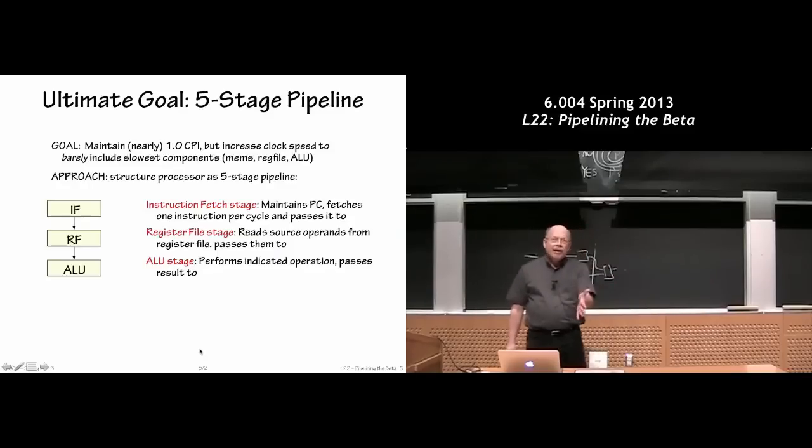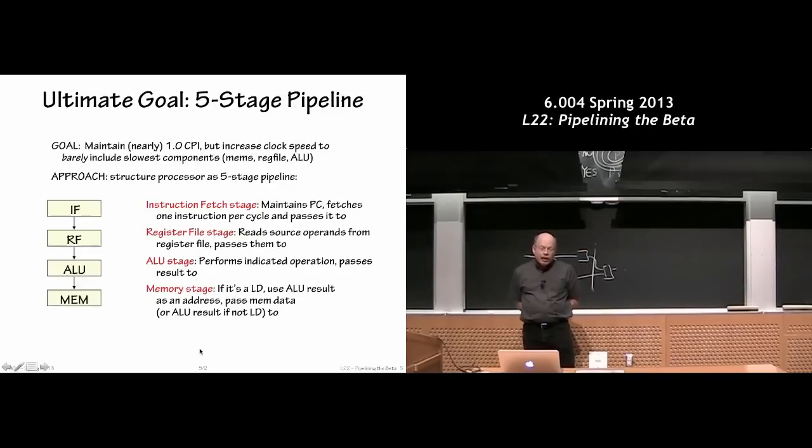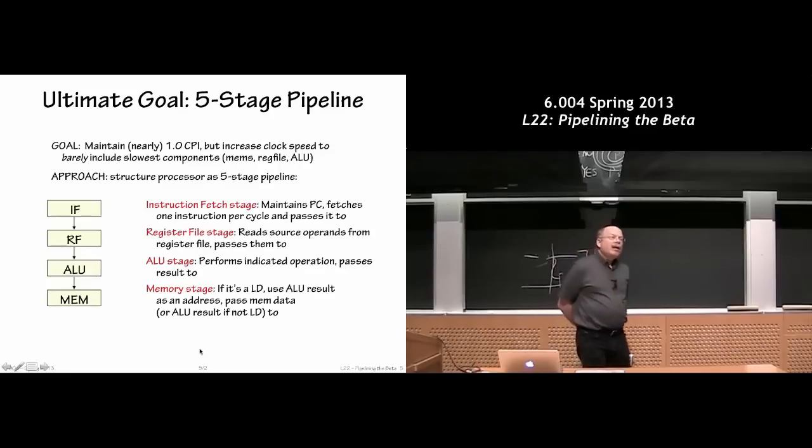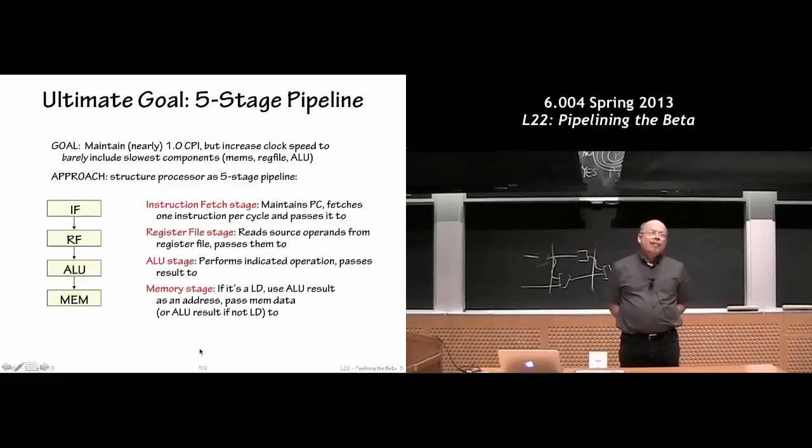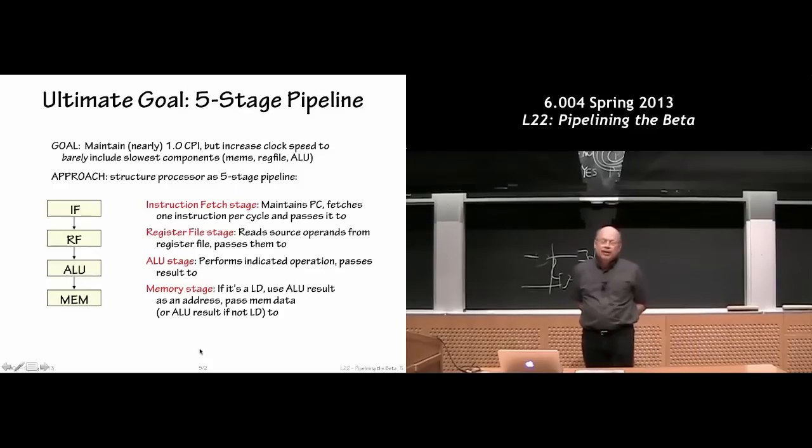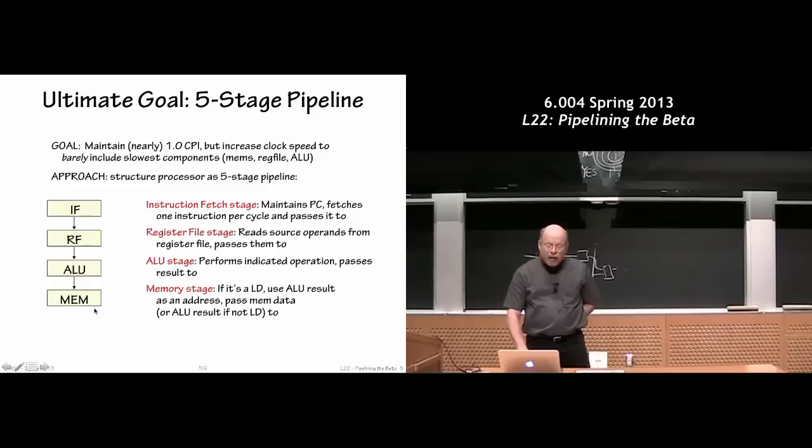Once we have the result from the ALU, for certainly the load and store instructions and the LDR instructions, we have to put in a step which is not needed by all instructions, but assuming that we use the same recipe to execute each instruction, we have to leave room in our recipe for loads and stores to go take the address computed by the ALU and fetch the corresponding data, or write new data into the location addressed by the result coming out of the ALU.